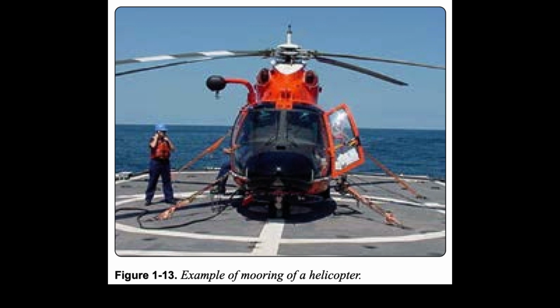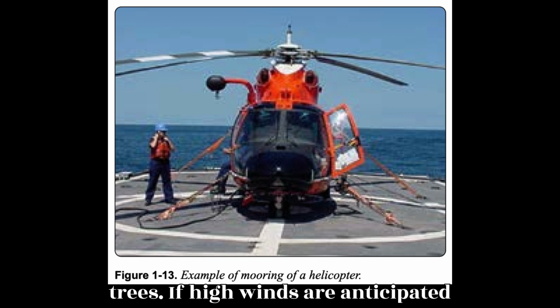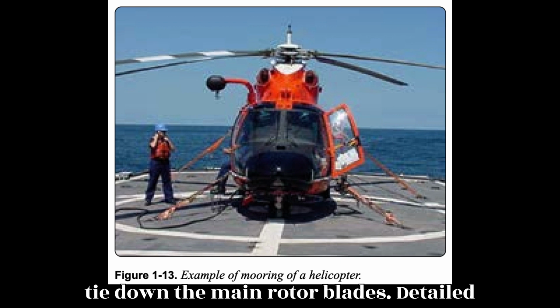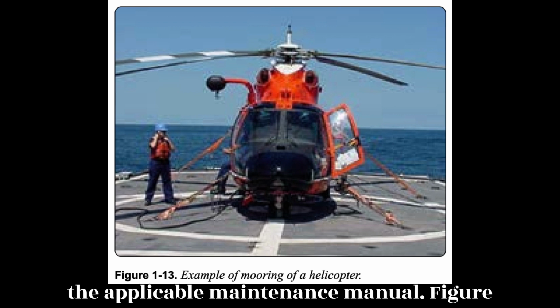For added protection, helicopters can be moved to a clear area so that they are not damaged by flying objects or falling limbs from surrounding trees. If high winds are anticipated with the helicopter parked in the open, tie down the main rotor blades. Detailed instructions for securing and mooring each type of helicopter can be found in the applicable maintenance manual.